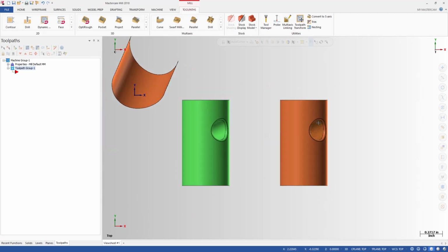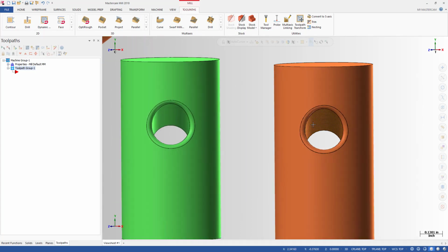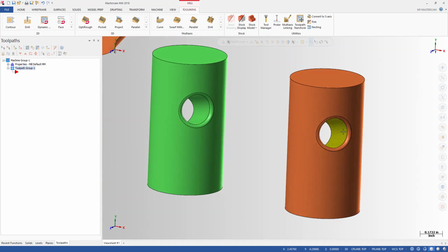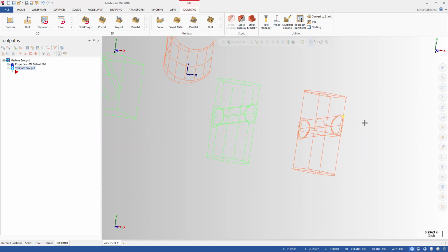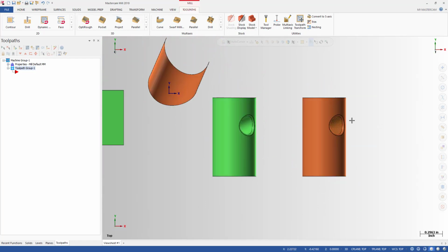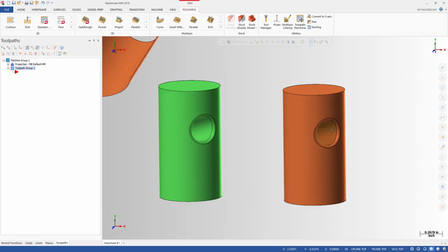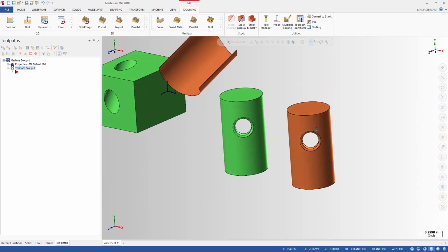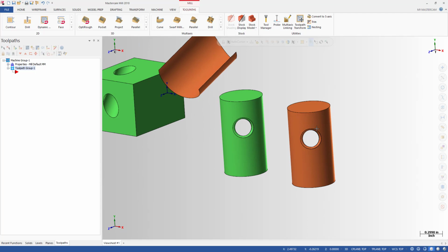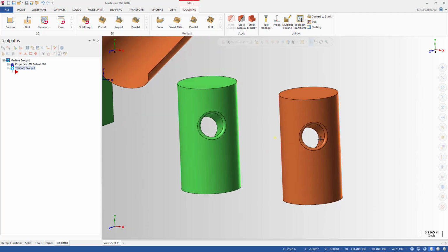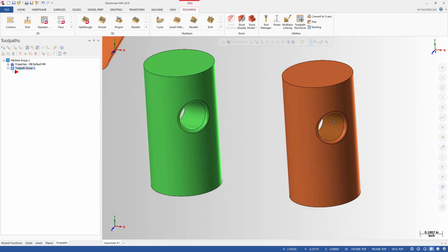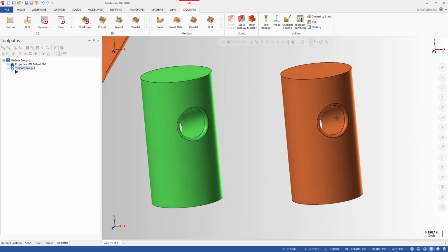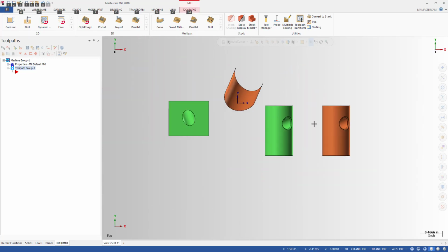And when you work on surface and you want to find the center line of one hole like this, for example, I have one hole here, it's not straight, it's a little bit tilted like this, and you want to create a center line here because you want to drill or something on 5 axis, so you have to make a plane and drill. So you want to find the center line of this hole, so this is how we do.